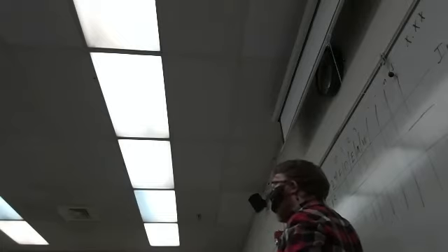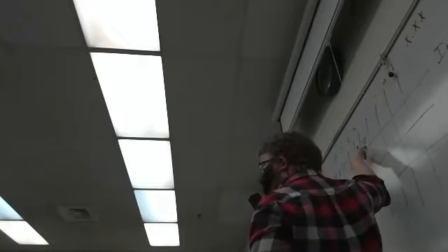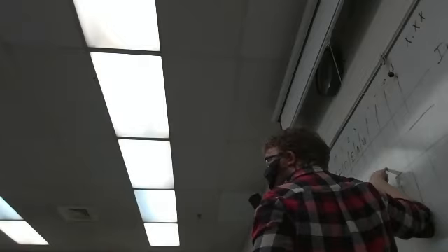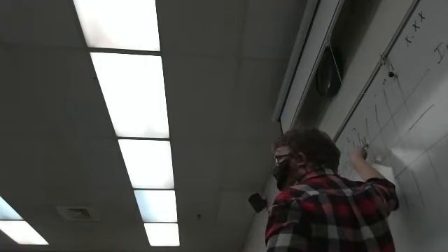So what I would do is identify the problem location, which is 6, and then identify at what point this will be ready. Well, we know at this point is where we're storing it back in the register. So at this point, 6 is not ready. It will be ready the next clock cycle. So the step where we need it to be ready: I can't read and write from that register on the same clock cycle.